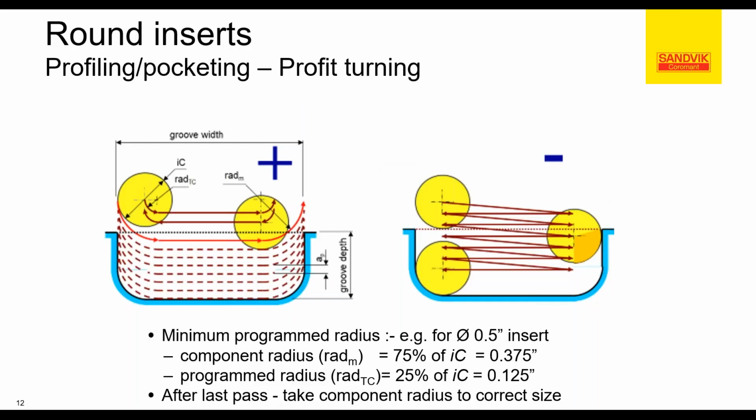Now, profile turning. And we saw in ESPRIT, profile turning is extremely flexible because you can control your arc and radius either by the radius of the tool or by the percentage that you put in. It's very important that you make sure that you use those, and you want a light engagement when you're doing the profile turning. This allows for a thinner chip where you can actually have higher feed rates and utilize the speed of the machine to get the material out. And we clearly saw that in the video that Kevin had shown versus a ramping.